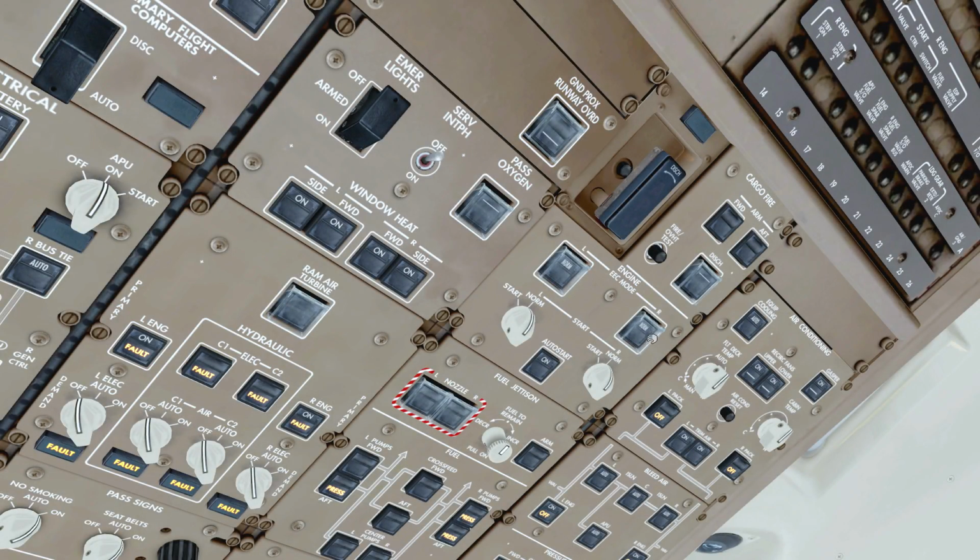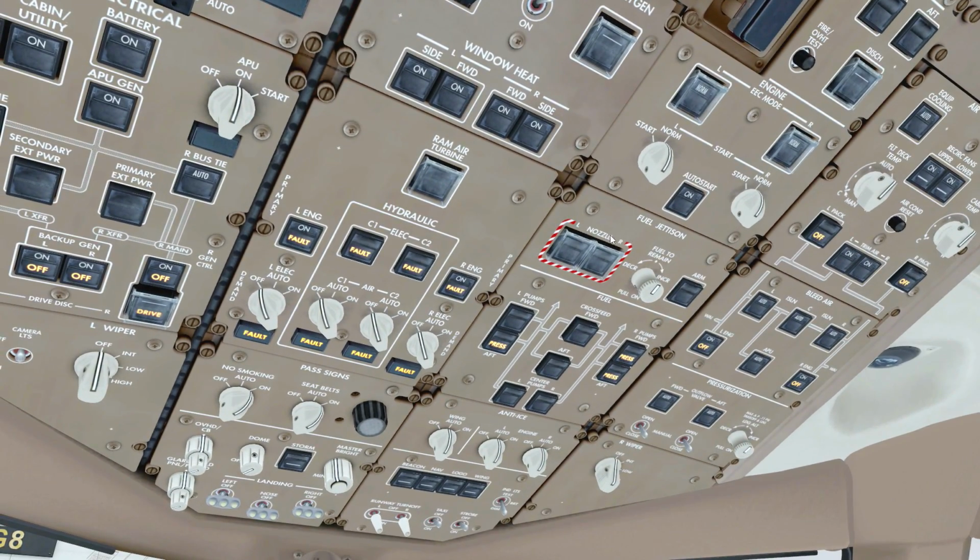Again, you can leave these switches, the EEC mode switches, closed, just stay on normal. And then we have the start panel. Now, depending on which type of airplane you're exactly using between the 777 versions, all this may look a little bit different. In this case we do have the auto start function. Just leave that on. We're going to use that during the engine startup, and basically we're going to use these switches in a moment in order to start the engines. Fuel jettison panel. This is of course for fuel dumping.